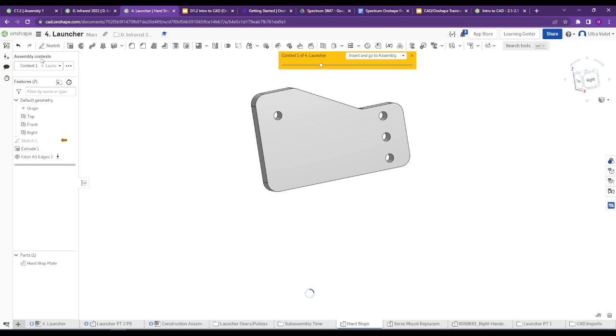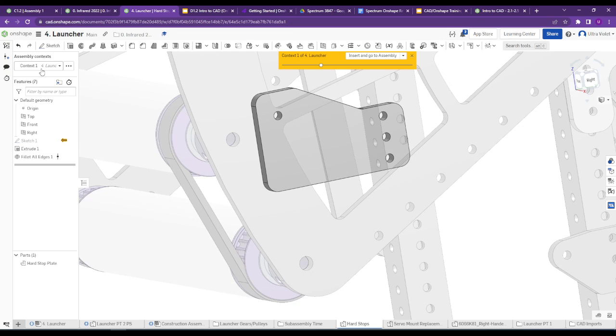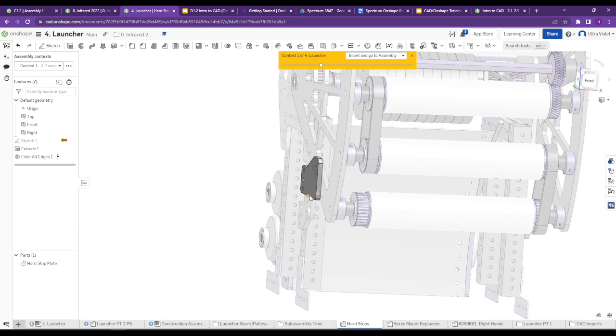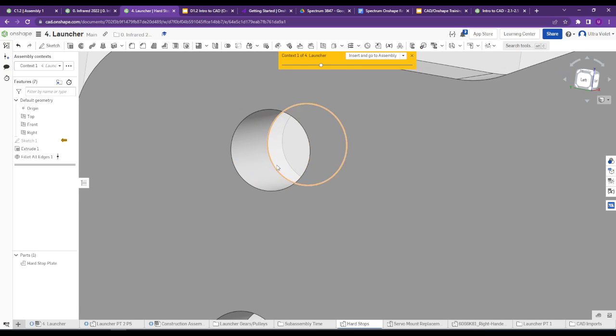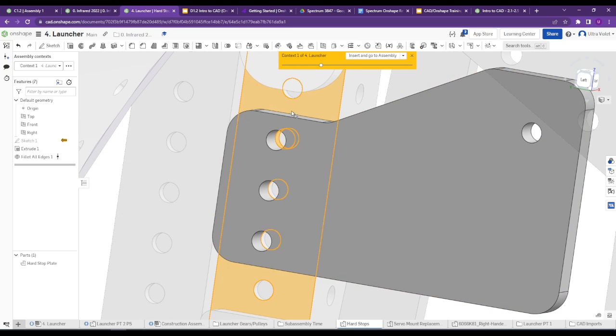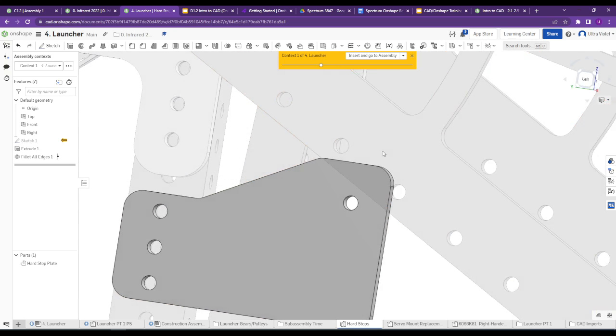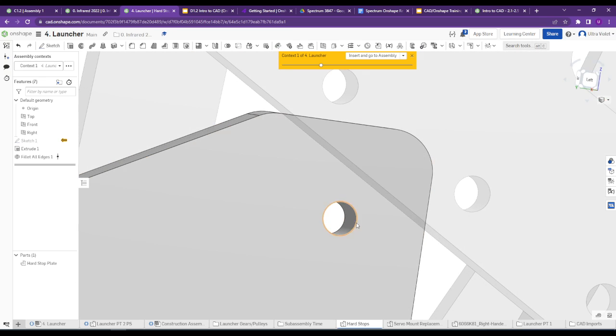This has this little assembly context up here. You can actually have different contexts, so if you have multiple assemblies you're basing it off of, or maybe they're in different positions, you can do that. Most of the time we only use one. But this allowed us to use these holes from this tube that already existed, to figure out exactly where this hole should be so that we could make sure the part we were going to put on here rested on here correctly.